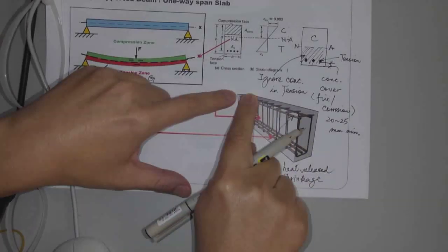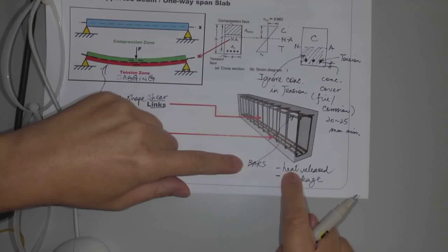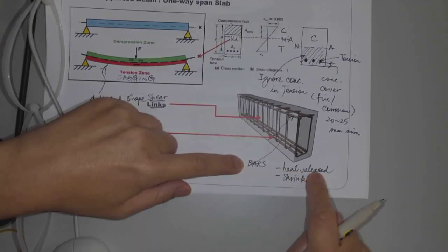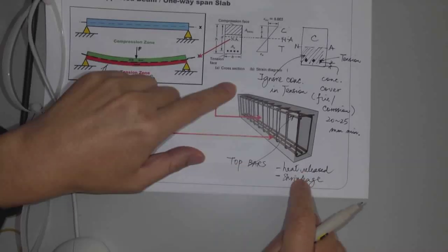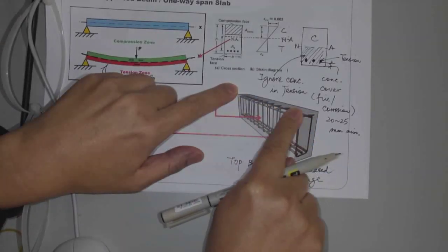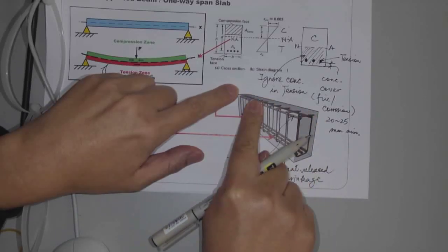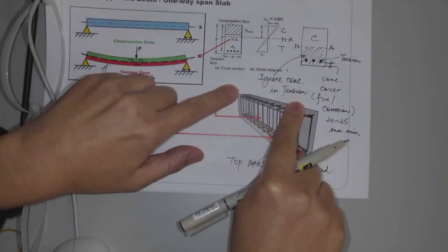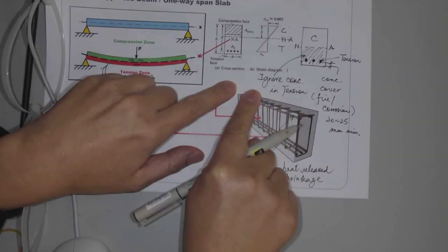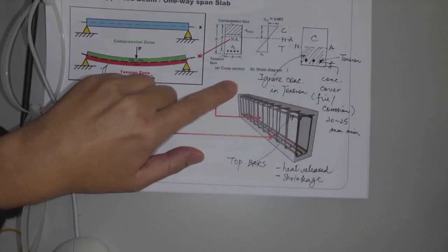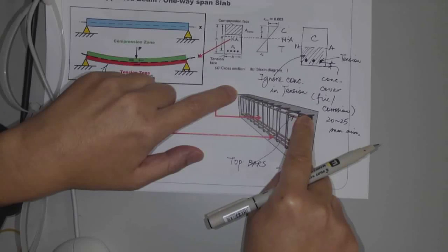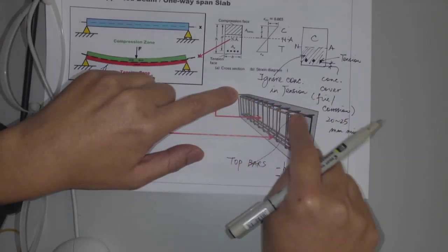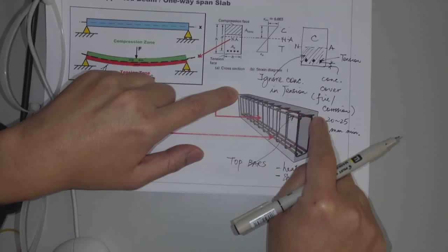If you don't put reinforcement there, what happens is when the temperature changes due to the heat release and the shrinkage, when these two things happen, there will be tension developed at the top surface, actually at all surfaces. So to protect the top surface from cracking, when there is tension, there will be cracking. You must put reinforcement there, right? Otherwise, when the hardening is done, it cracks everywhere.